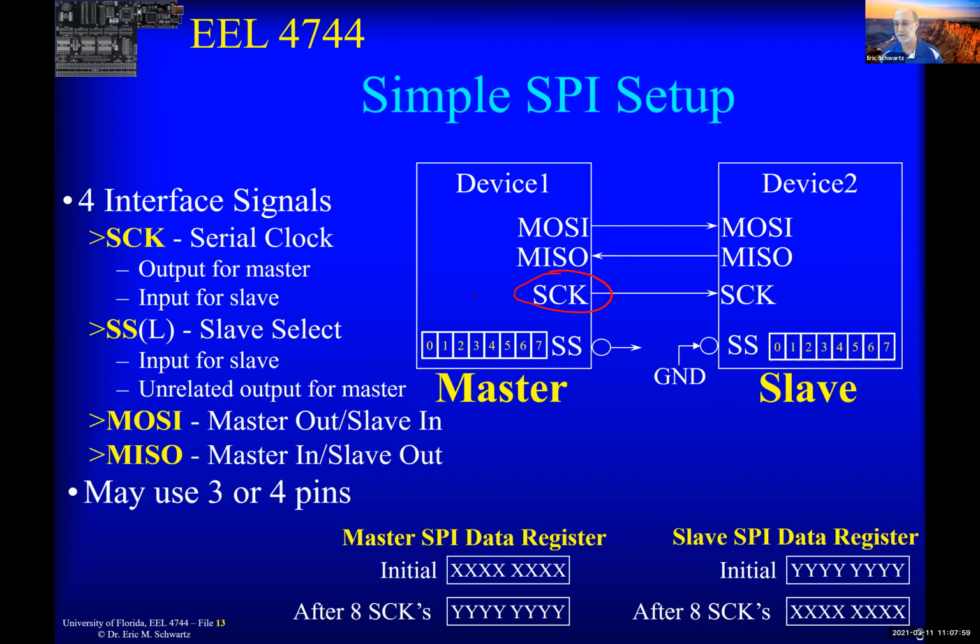That's what triggers everything. Now, there is a slave select pin that all masters have, because what if you wanted multiple masters? Then one of the masters would take charge and make the other masters slaves. But typically, most systems have a single master. And if there's a single master, then we can make the slave select pin an output, and there's no worries about it ever going low. Because if this pin is an input and it ever goes low, it basically freezes everything, because the master is now being told you're no longer the master. So remember, all pins by default are low.